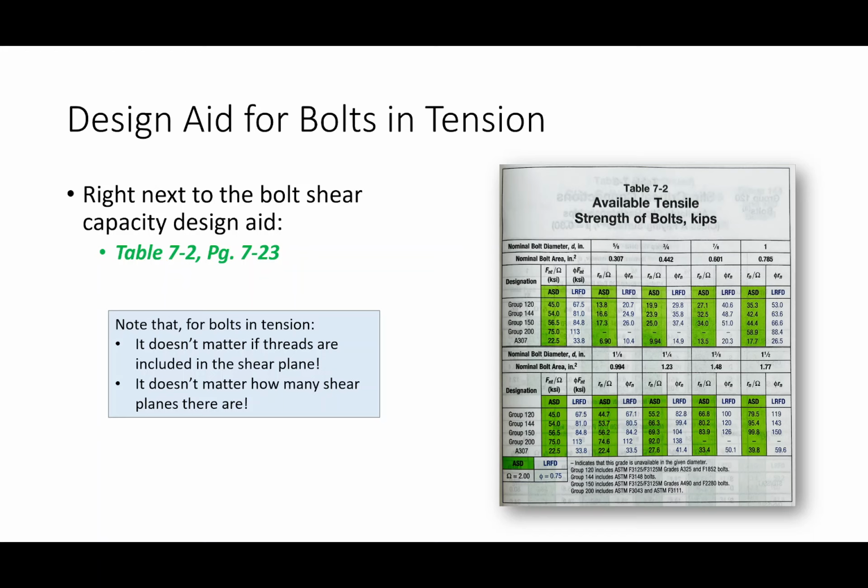Same thing with tension. If we have a bolt group experiencing tension, take the tensile load per bolt and compare that against the tensile capacity per bolt. Again, you could do a performance ratio, but just check each one at a time. But that doesn't quite answer the question about interaction.